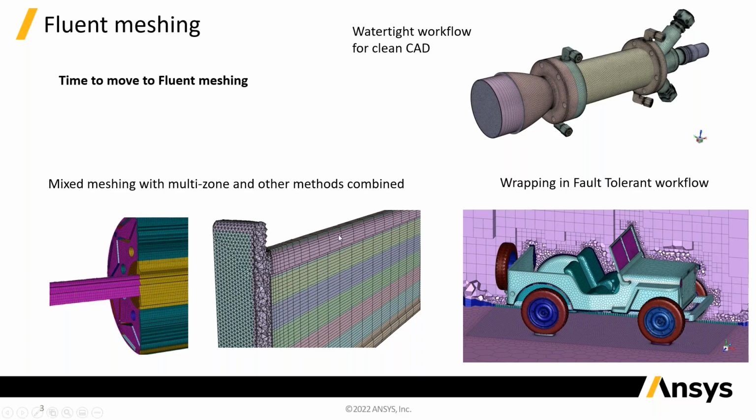Now, coming in the very latest release, just come out, is the ability to bring multi-zone meshing in here. So these are hex core, but suppose we want to actually have some sweep mesh, and that's quite common if you've got thin components. You can now designate regions that you apply this multi-zone mesh on, which is essentially a sweep mesh. So there's now a very powerful set of tools, and if you're doing CFD, you really should turn to Fluent Meshing as your meshing tool now.